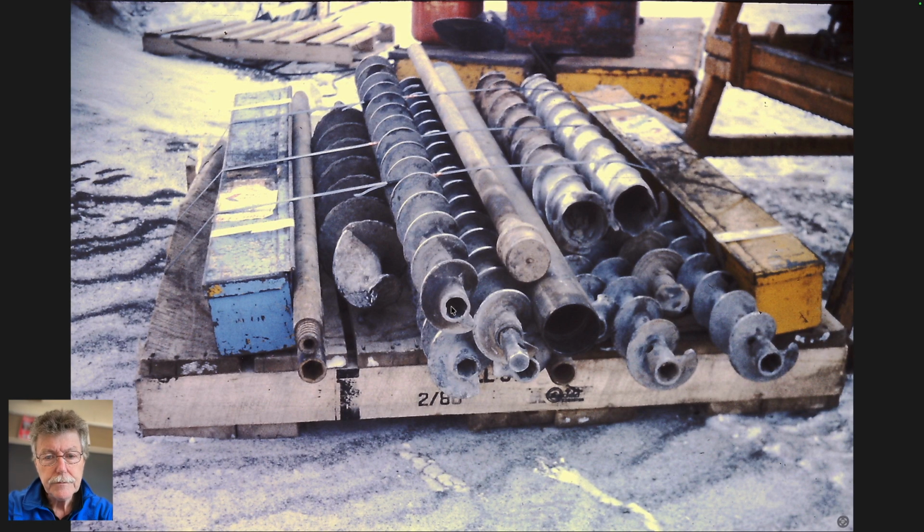Solid stem auger, hexagonal male coupling and female coupling. The hole here is where a pin goes through, so they go together. They don't twist next to each other because there's no thread, but once you put them together, you can put a pin through the bottom of this part here into the top of this part here. And so it's solid, and the pin can just be a solid steel pin that goes through here.